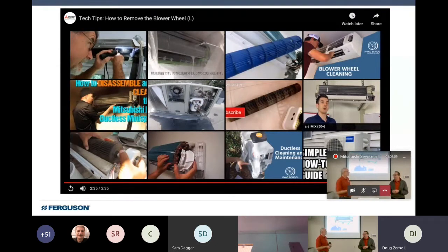Right, and another tip that a guy in the field who worked on this all the time taught me: if you look at that drain pan in that picture that's still there, you can come up over on this edge, and he uses just a small nylon tie strap to take the weight of the drain pan that's hanging off of the cables.